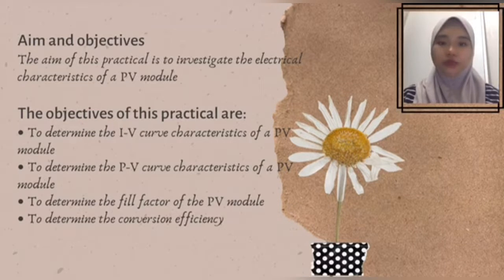And the objectives are: first, to determine the IV curve characteristics of a PV module. Second, to determine the PV curve characteristics of the PV module. Third, to determine the fill factor of the PV module. And lastly, to determine the conversion efficiency of the PV module.